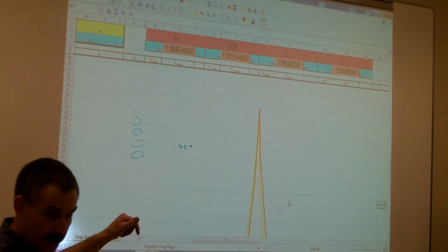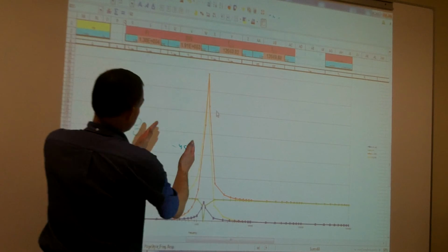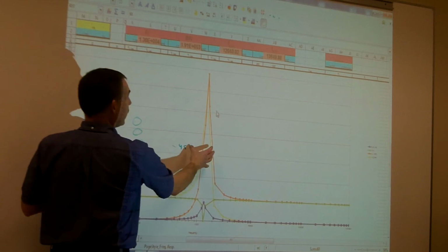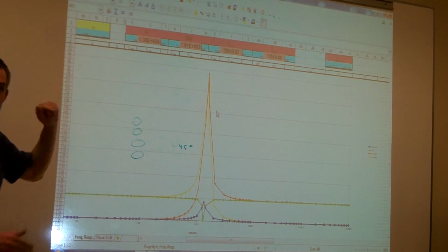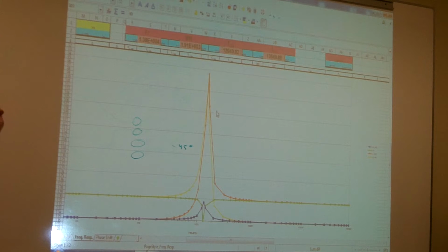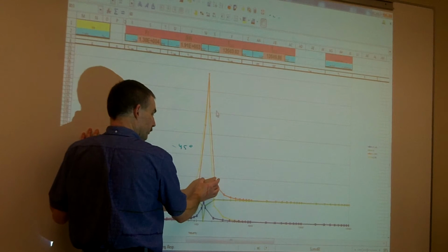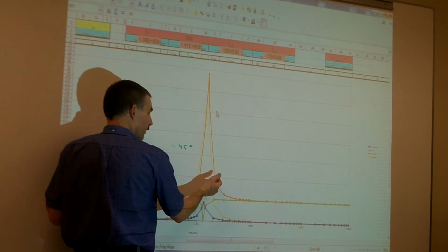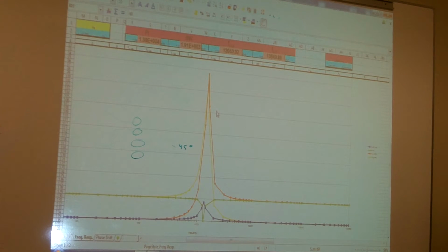And then you can see what happens now is that this gets to be wider. Okay, our quality of our circuit goes down and our bandwidth is going to get larger. So as I increase the resistance in my circuit, the wider the bandwidth. If I have to be very selective, that's what we consider our sensitivity. How selective is our filter? Sometimes we don't want to be so selective that we can't ever stay tuned onto that frequency. So we do want to have some bandwidth, but we don't want it so wide that we're picking up other radio stations on the other side of our bandwidth.